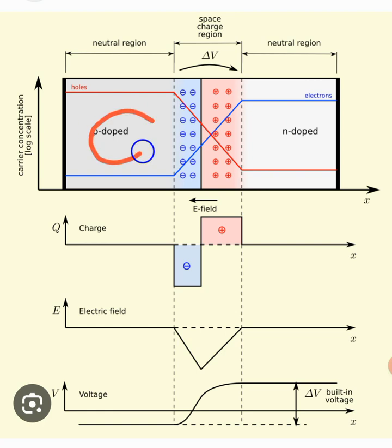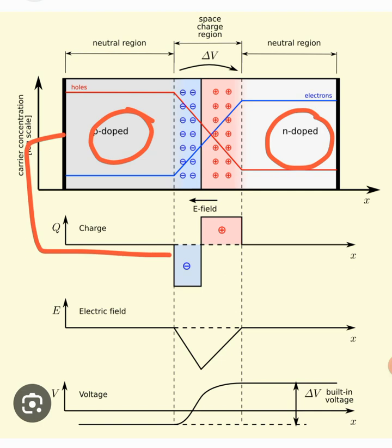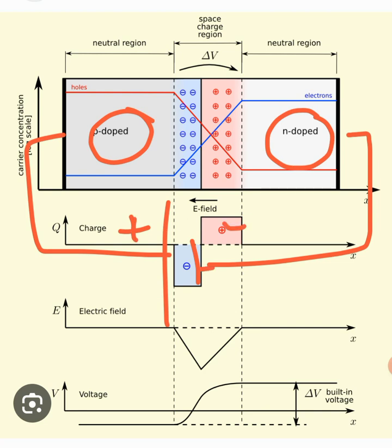So you have this P type material, you have N type material, you apply an electric voltage across this material, and because of that you have a positive terminal and a negative terminal, the current will flow, and the electric field will push the holes, and they will cross the barrier and go to the N type material.